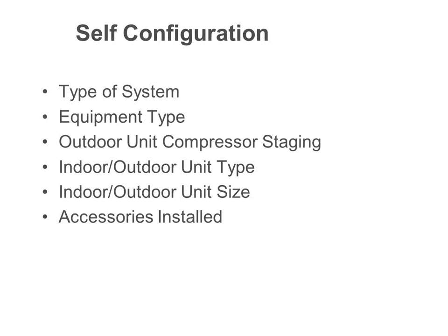It'll also help you configure control for accessories. Now, it's not going to automatically recognize your humidifier or something like that, but it'll ask you, hey, you got a humidifier? If you click yes on the screen, it'll configure itself for humidifier. It'll put all the humidifier set point tables and everything into the stat, and it'll be ready to go and ready to energize that humidifier off of that extra relay in the furnace. Same thing for filtration and air purifiers and all that kind of stuff.